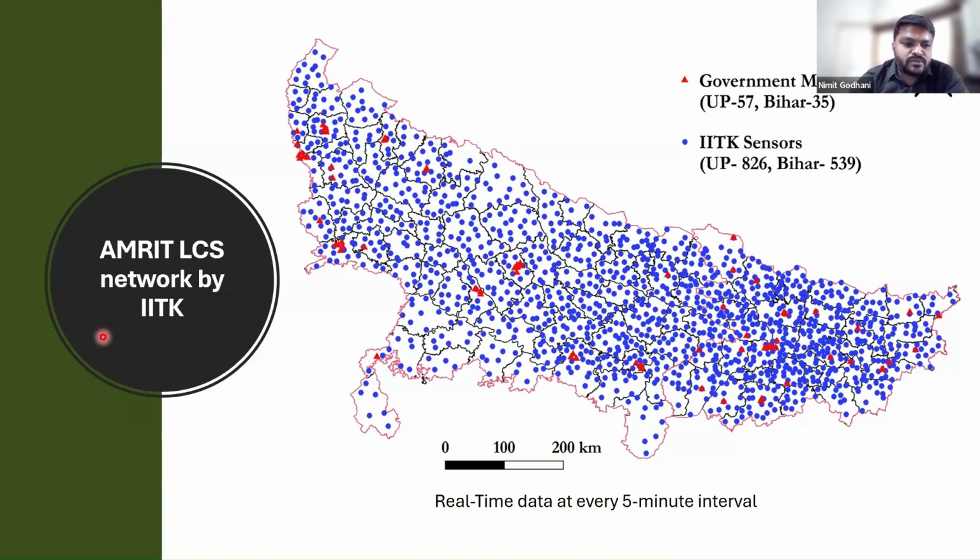One thing I want to mention is that in highly polluted regions, they have a different calibration factor for each range. Suppose your PM concentration varies from 0 to 200, then some calibration applies, and for 200 to 300, another one applies. We are working on that also, because sometimes humidity affects the most. One criterion we see is humidity of more than 75%.